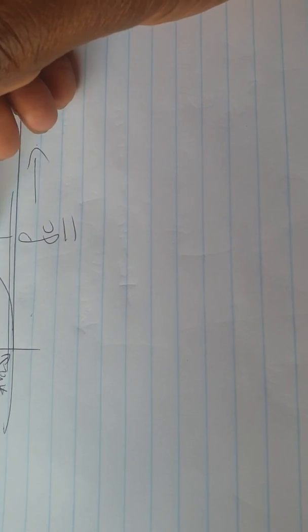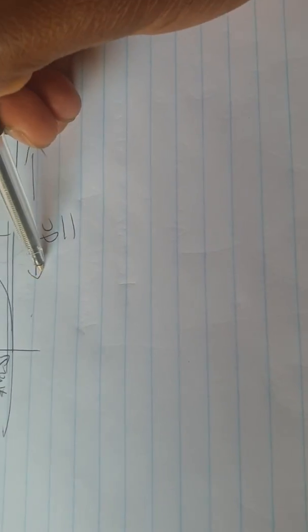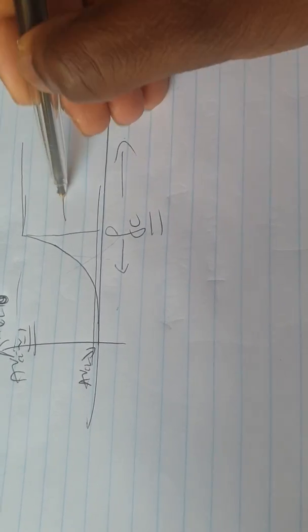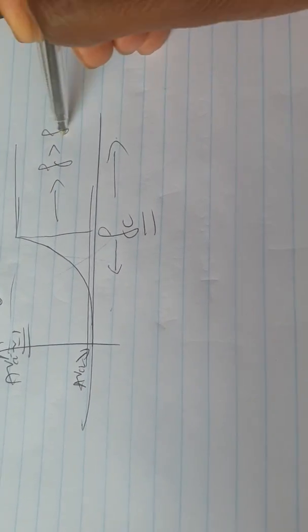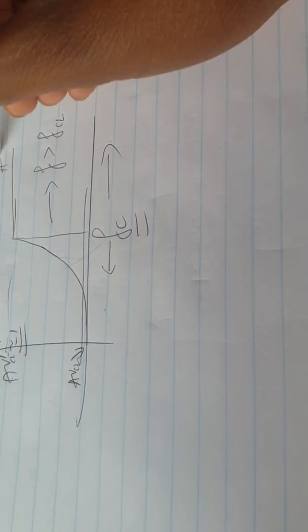So you pass the component of the signal with a high gain, while the others have a very small closed loop gain. Closed loop gain ideally equals 1. You drop the component of the signal with frequencies lower than a certain cutoff, and pass the ones with a frequency higher than the cutoff. And this is a high pass filter.